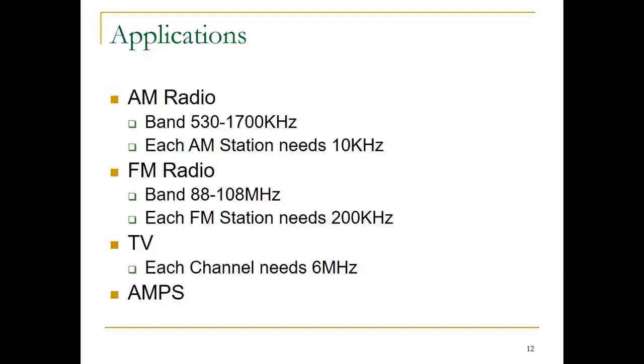Even though some of the frequency and time division multiplexing are being adapted within systems, I think most of the frequency allocation for mobile services revolves more or less within the time division, so we can utilize the frequency much more efficiently. So when it comes to the AMPS part, current mobile services or mobile technologies adapt the time division a lot as compared to the frequency. Okay, so that covers the application part.